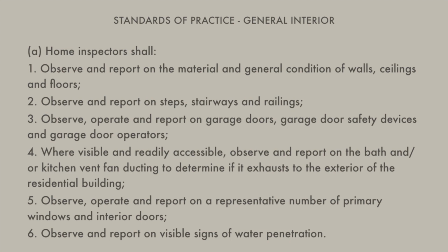Where visible and readily accessible, observe and report on the bath and/or kitchen vent fan ducting to determine if it exhausts to the exterior of the residential building. Observe, operate, and report on a representative number of primary windows and interior doors. Observe and report on visible signs of water penetration.